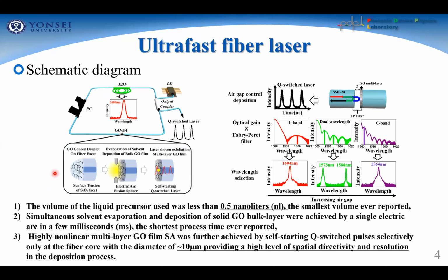First is how to make a thin film deposition like this. And this is the conventional laser cavity, making CW laser generation. But when we add an optical component, the saturable absorber, we can make short pulse lasers.